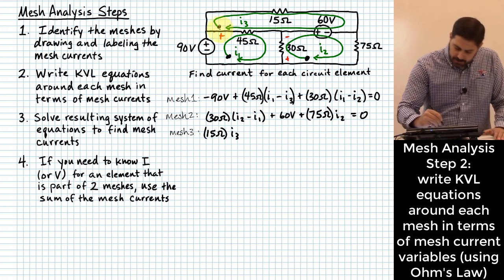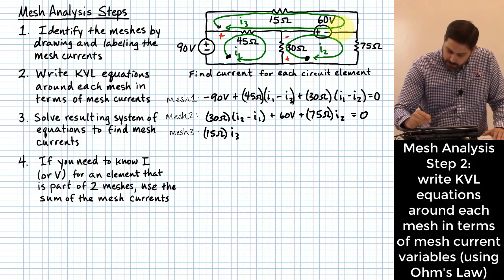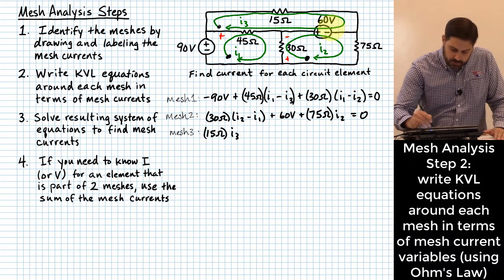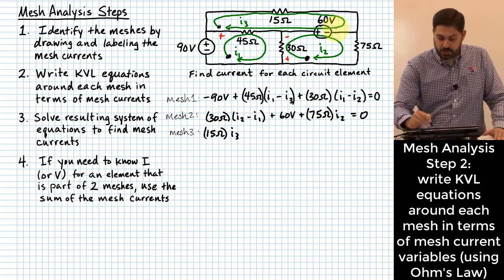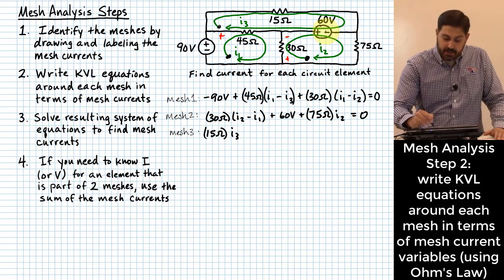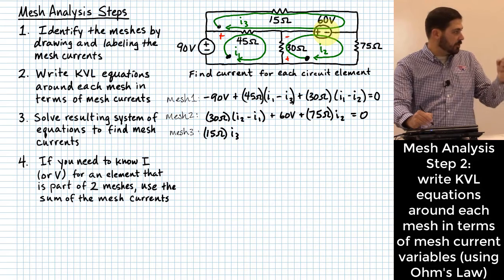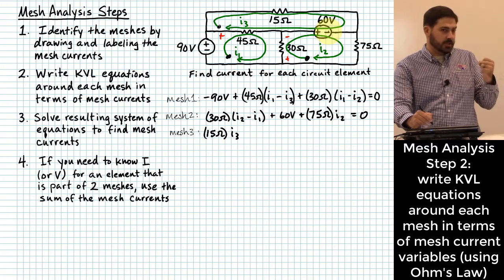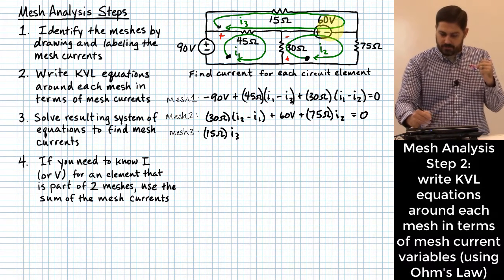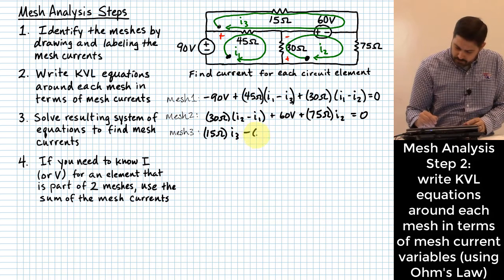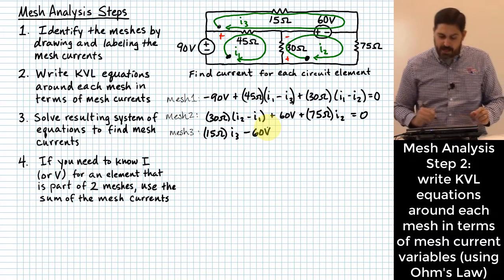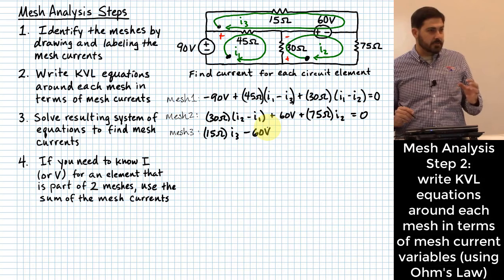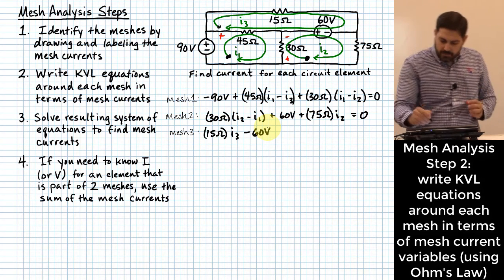Okay, I'll keep coming around the loop now, and what's the next thing I come to? The 60 volt source, but now I come to the negative sign of the 60 volt, the negative terminal of the 60 volt source first. So how do I count it in my loop? Okay, negative, we'll count it as a minus 60 volts, right? Then what?